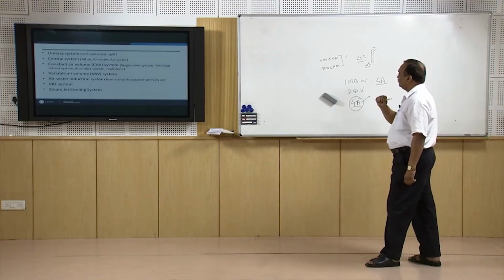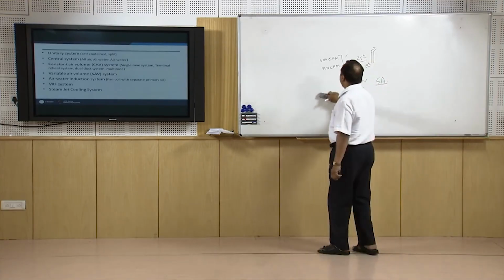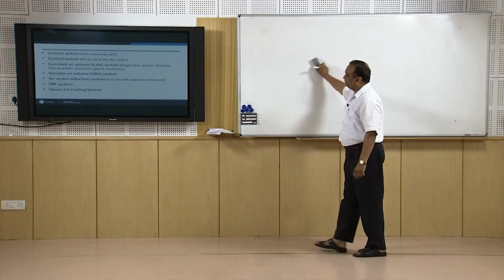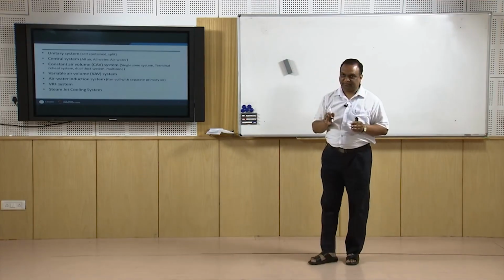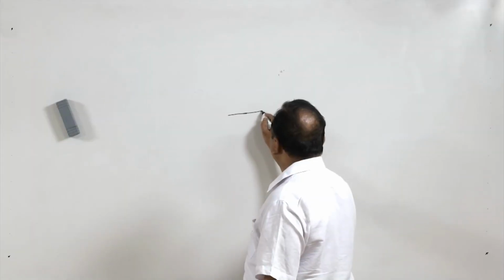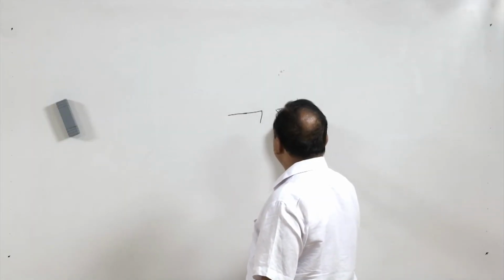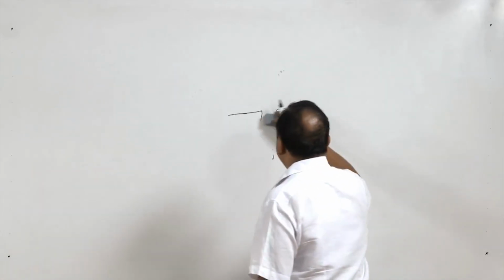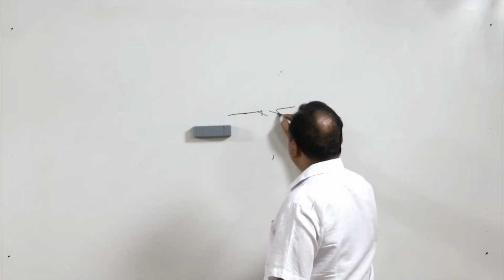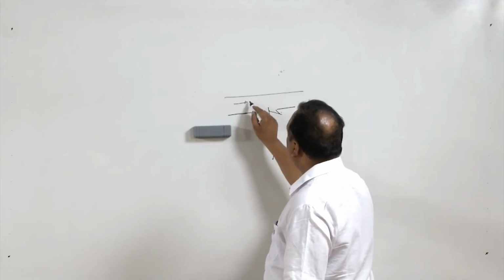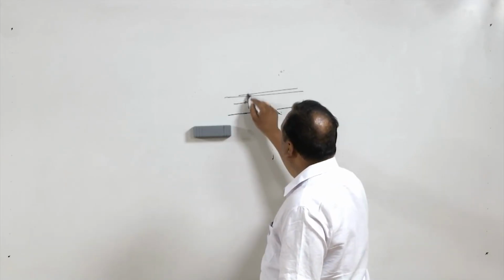So we are talking about the variable air volume system, where the volume of the air changes, right? When the temperature inside the space reaches the required temperature and we no longer require cold air, the dampers start closing, and the static pressure in the duct increases.